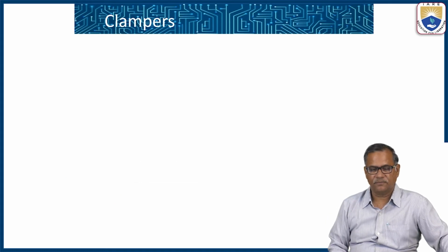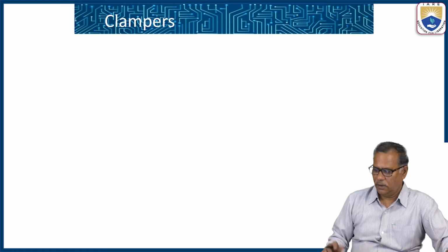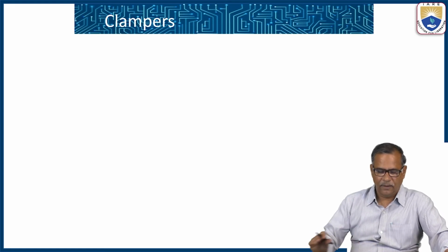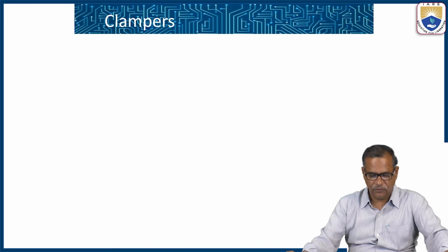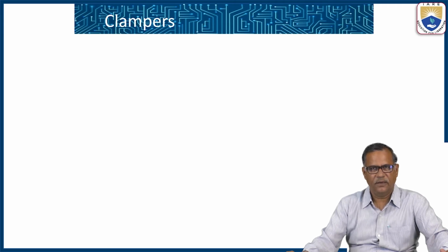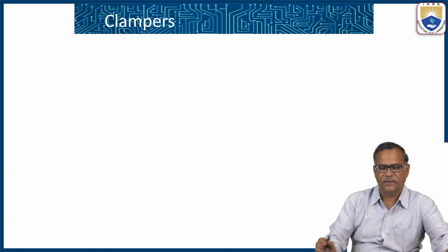Now first, when you have to clip the signal at plus 10 volts, then we have to design a positive clipper circuit with positive reference voltage.